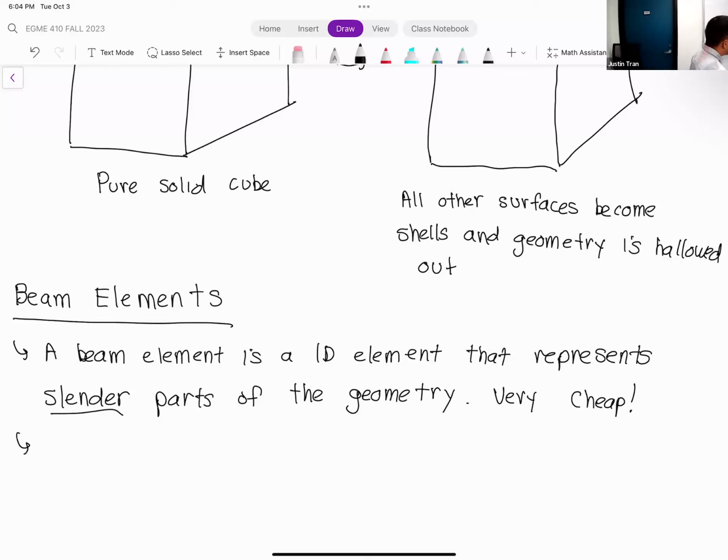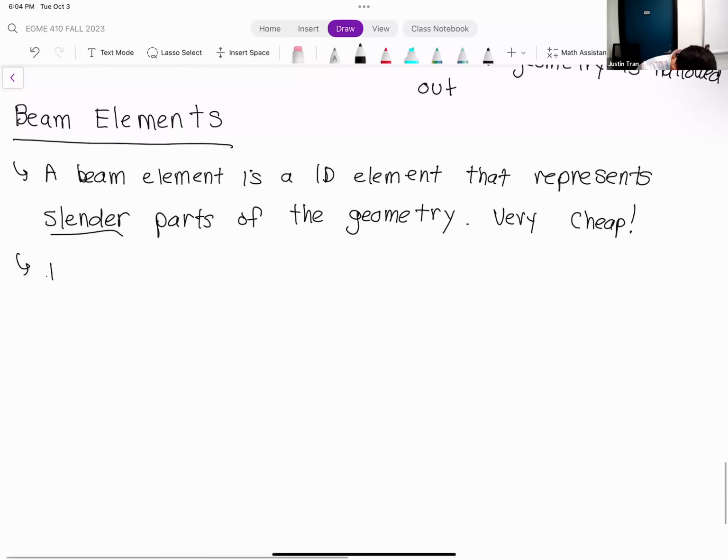But because they're basically a 1D representation of a 3D geometry, okay? It has to store more information internally, more so than the thickness. Okay. So internally, a beam element needs knowledge of not only its thickness, okay, but it needs information about its 2-dimensional cross section. Okay.